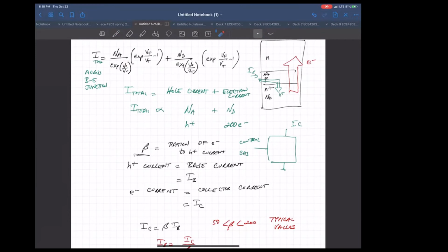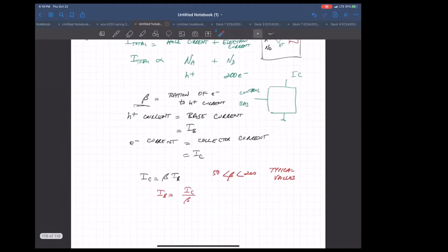And to some extent, the secondary effect, if you start taking semiconductor classes, you'll see there's some recombination. A few of these electrons will recombine with holes here, so not all the electrons will make it all the way through. It'll depend on the recombination rate in the base, but that's a secondary thing. Most of it is the doping concentration differences between the base and the emitter. So if it's on the lower end, do we say it has more concentration in the base or emitter, or vice versa? Yeah, or it could be you're getting more recombination. Okay, that's right. Thank you.